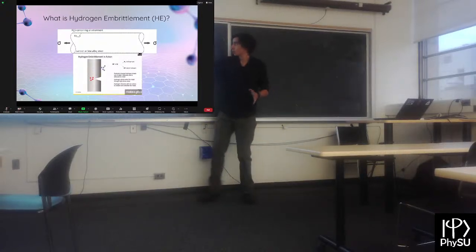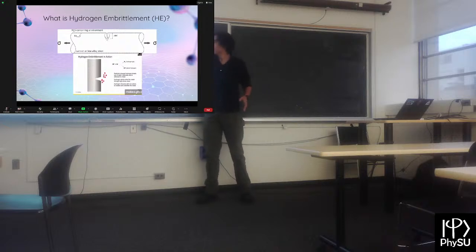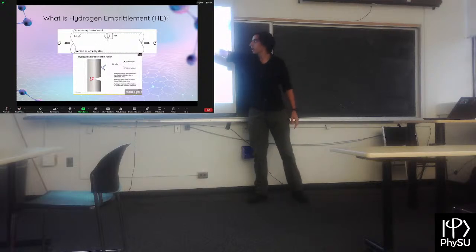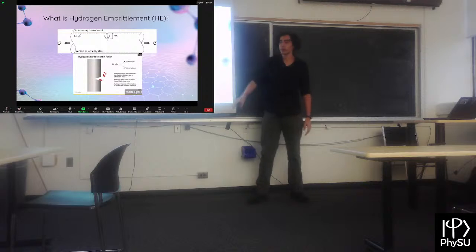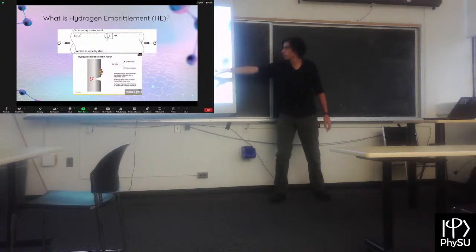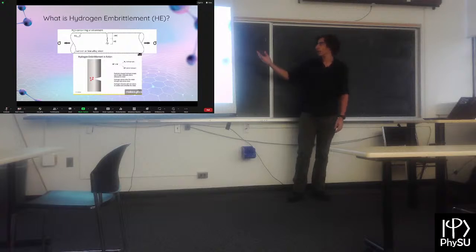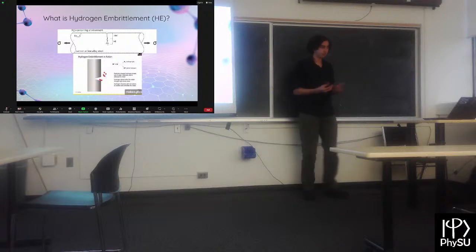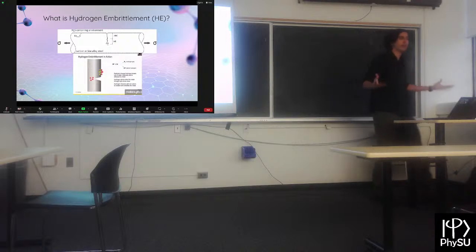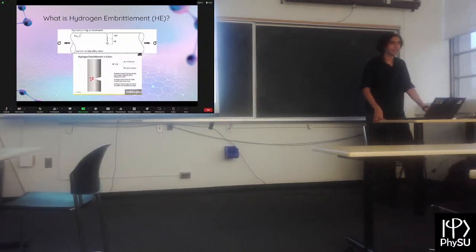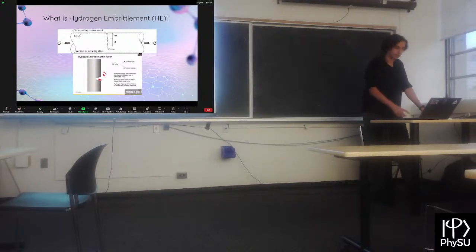For example, here we have a metal pipe in an environment that is rich with hydrogen, and the hydrogen enters different cracks, different dislocations, grain boundaries, and makes the cracks worse, continues propagating those cracks, causing the metal to essentially crumble. It's embrittlement, essentially. Its ductility is affected and it does not perform as well in tensile tests.